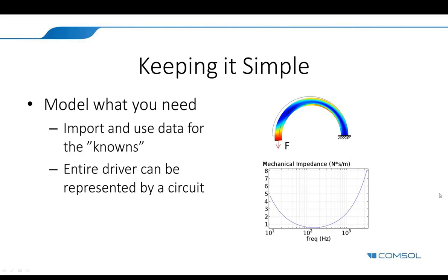Can you investigate what is the root cause for the spike in the frequency response at 700 Hertz? That's very observant of you. I've done that already, actually. What happens is that we get an unwanted Helmholtz resonance right in between the core and the cone of this loudspeaker.